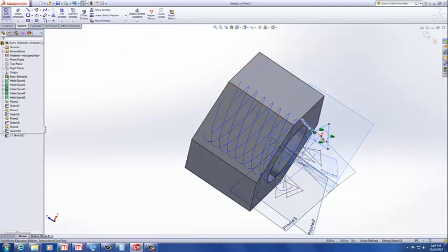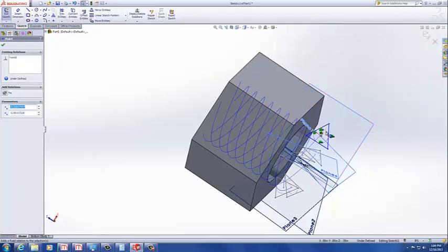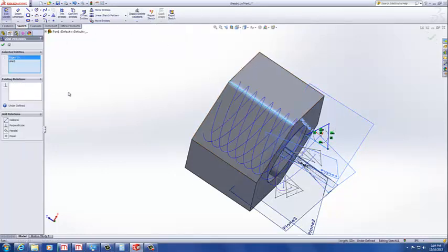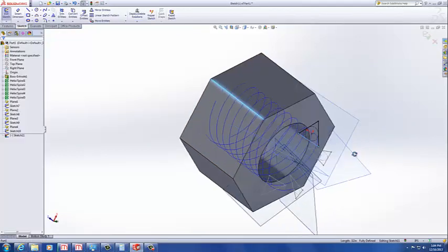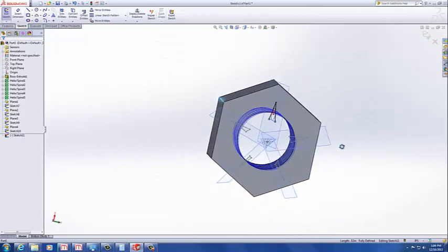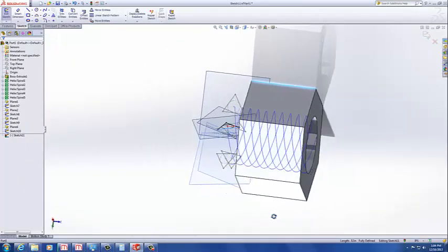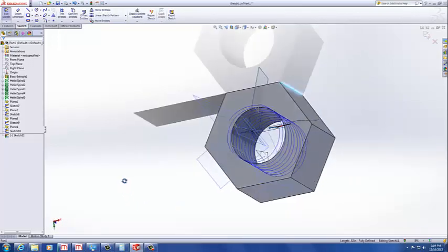And then that selection, let's anchor the point, anchor the circle, grab this line, add a relation right there. Let's make them parallel. There you go. So now your design should look like this. You should have all the sketches ready to be used for cutting out the threads.